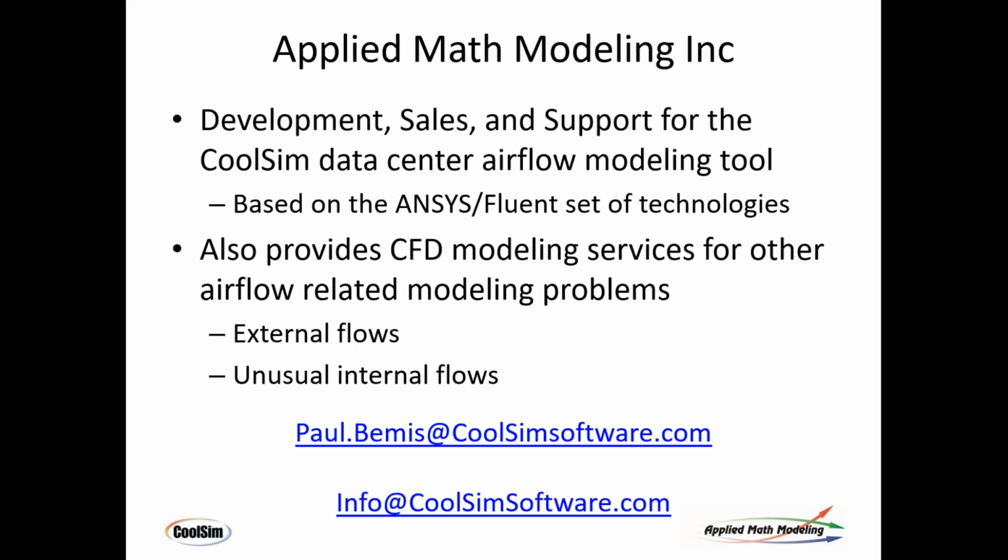So vapor plumes can be modeled. The only thing that we would need as an input is the size of vapor particles in the plume that is coming out from the cooling towers. Or if we do not have the size of those water droplets, then we can assume a bell curve and then do the simulation. A bell curve, yeah. So you would assume some sort of distribution, because it's probably higher in the middle and lower on the edges, so you're assuming a bell curve distribution of vapor as a boundary condition. Yes, please.